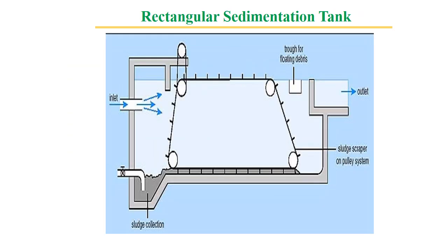So this is another sedimentation tank. It is just like a large-size pond. Sometimes it is made of concrete, and the earlier one was circular. This one is rectangular. Here the water is allowed to settle down. All the solid, heavy particles are allowed to settle and are collected as sludge. Then the water still has a lot of dissolved substances and organic matter, which cause pollution and BOD. That is removed through chemical and biological treatment.